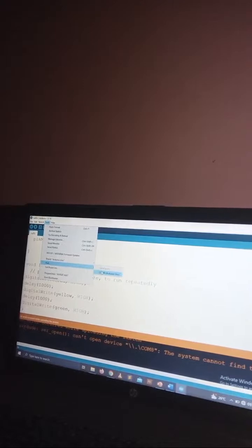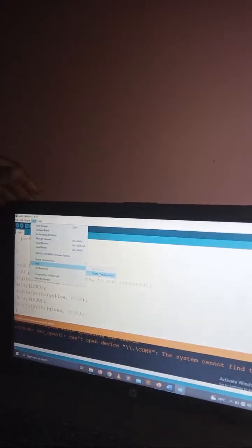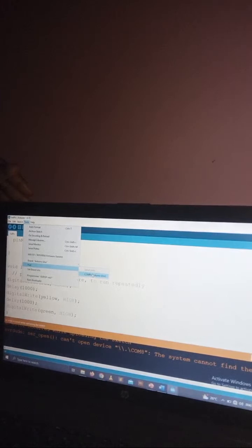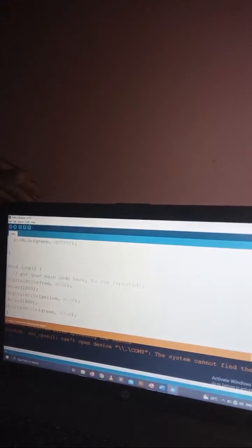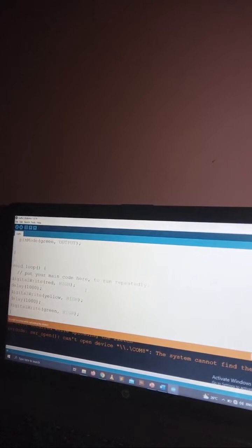Once you connect your Arduino to the system and go to the Arduino IDE, you'll be able to see the name of that port. The port of the Arduino I'm using is COM9, communication port 9. So I have to tick it to let it know that I should transfer this file to port 9. Okay, then this is the upload button, and I'm going to upload.